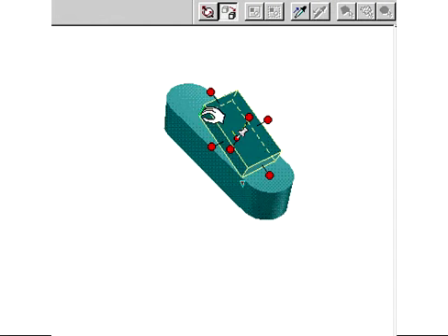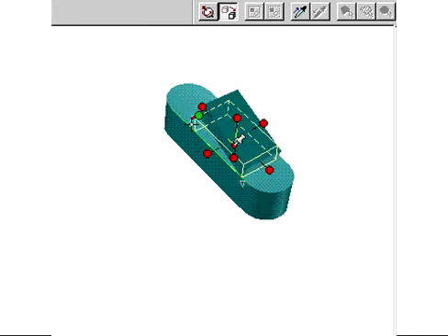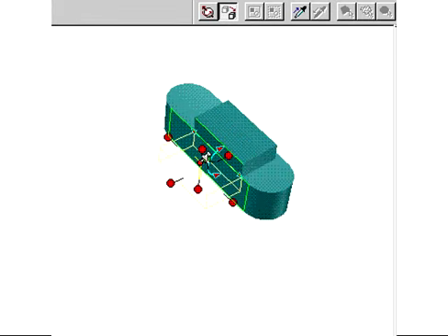Click and drag a second point to join the two shapes edge to edge. This further constrains the motion along the axis connecting the 2 points. Finally, repeat the process a third time to join the two shapes surface to surface.